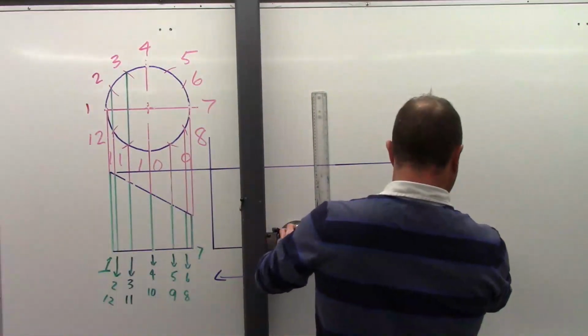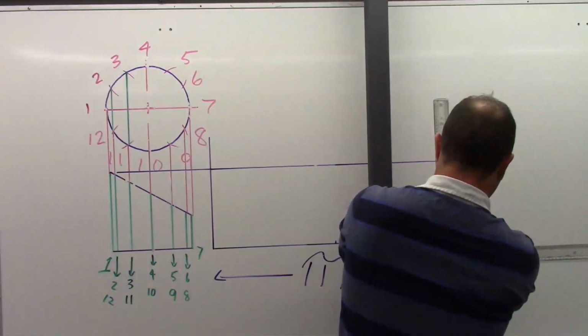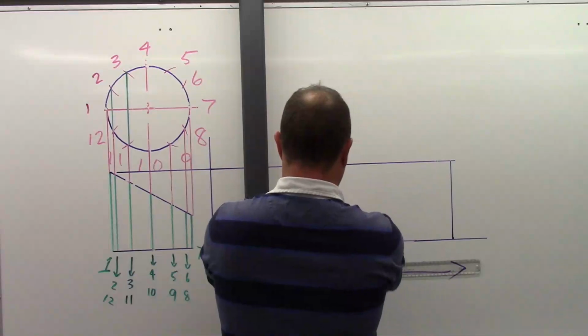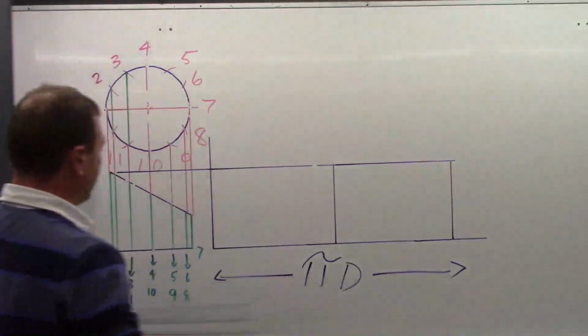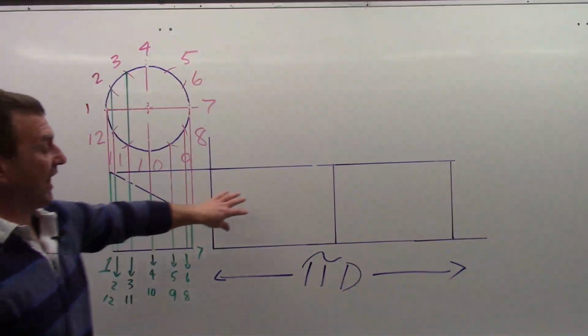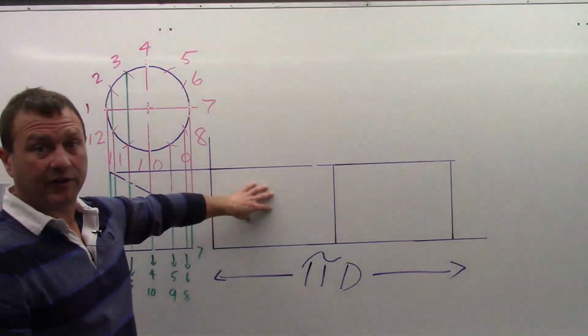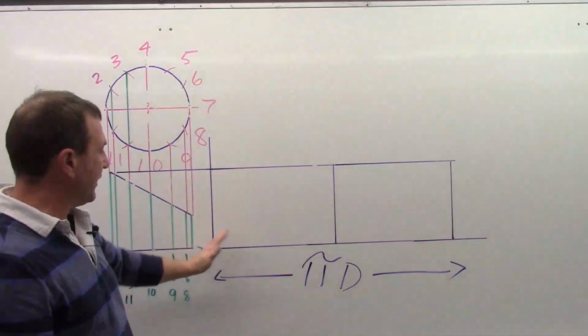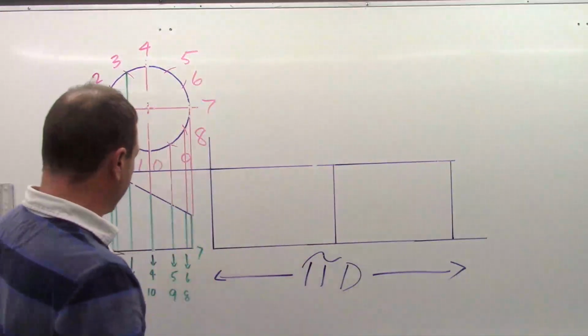And mark halfway again. And there's my end point. So now I have my full blank size calculated out and drawn out. So I have the height of metal I need for this way and the length of it for our stretch out here.